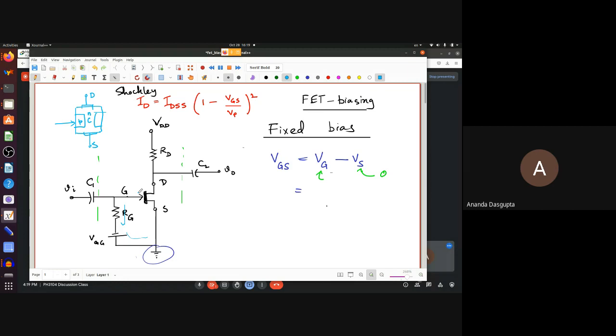Okay. So that is one of the reasons why the JFET has an advantage over the BJT. The JFET draws very, very little current from the input side. Through the gate, almost no current flows because the gate is always bound to be reverse biased when it's operating. And through a reverse biased PN junction, very, very little current flows.